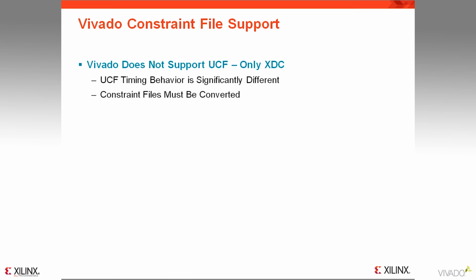Most ISE users will be familiar with the UCF constraint file format. Unfortunately, UCF is not supported in Vivado. The reason for this has mostly to do with timing constraints, and the significant difference is how the two are interpreted by the timing engine. A detailed analysis between these two is not the topic of this presentation, but suffice it to say that there is no guaranteed way for a tool to convert the designer's intent between these two constraint systems, so the designer must do it themselves. If the designer is familiar with SDC, a manual conversion is probably not difficult, but a large portion of our users have been using UCF for a long time, and this is not a trivial task.